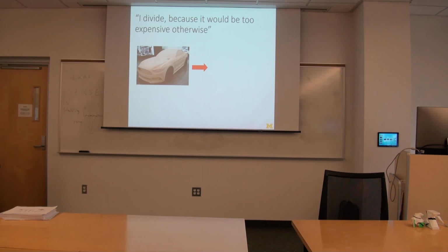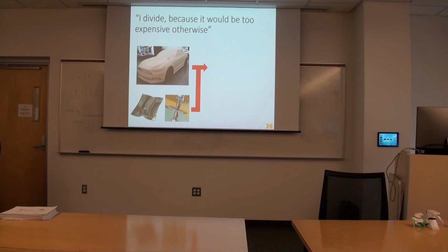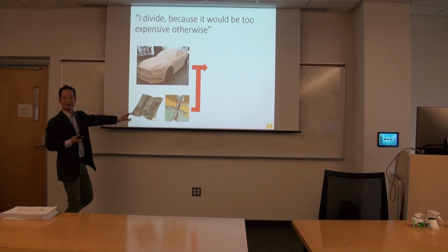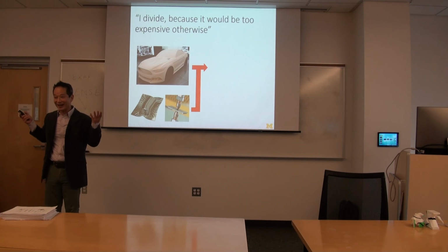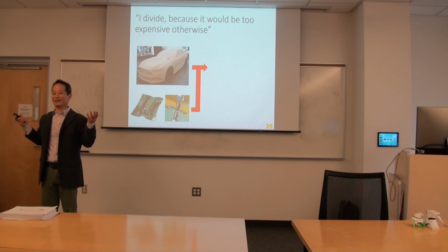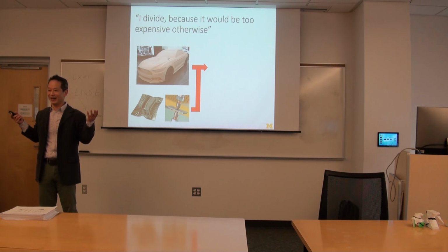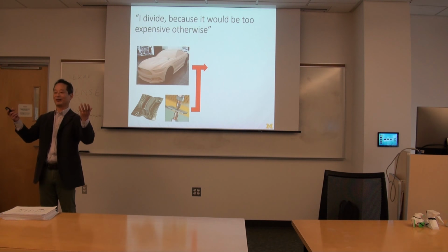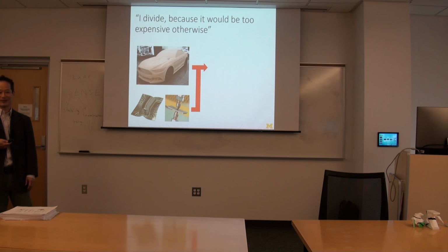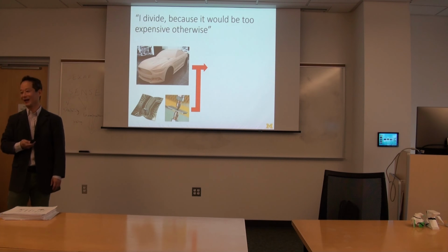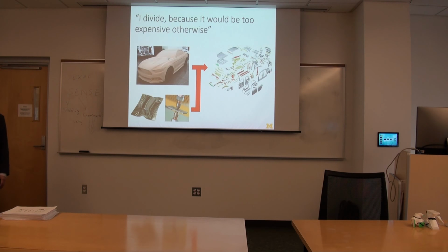So, yes, I will start with this clay model, one big piece, but then in between, the partitioning into 1,000 pieces of components, there's a decision that, okay, I would use sheet metal forming and spot welding to make it. Then, all of a sudden, because it's a sheet and it can deform only this much and has certain geometry and topology limitations, obviously I cannot do that. Because of size, it maybe cannot be too big, and the curvature cannot be too large, and so on and so on. It ends up being like this.